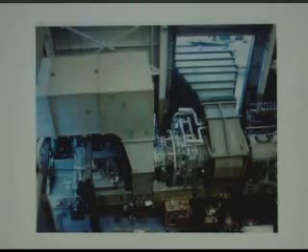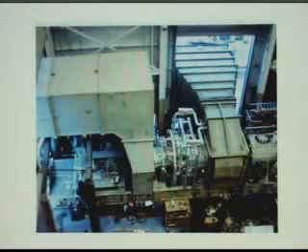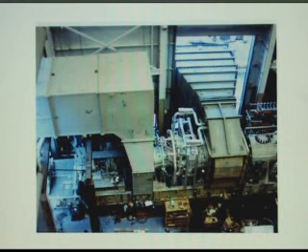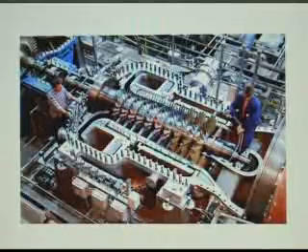But on this machine, you take this panel off and you walk inside the inlet plenum to gain access to the front end of the engine. Obviously, the engine is shut down and isolated. The fuel system has its blinds swung, and all the electrical systems are de-energized while you're doing this operation.